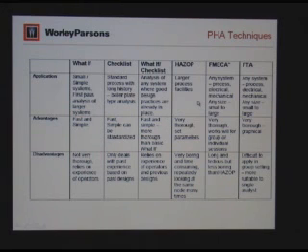And the HAZOP can be used for larger process facilities. It's very thorough, and you basically go through a set of already-set parameters, so as to avoid overlooking any item. The disadvantage is it's very boring. If you sit through a HAZOP, you will realize that's one of the problems.